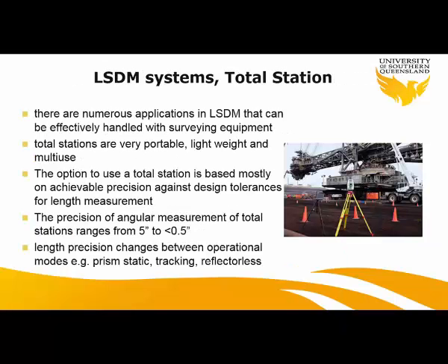The last tool, which we all know, is the total station. You might say a total station doesn't give you that precise a measurement, but we do have what we call an industrial total station, which I'm going to explain. It gives you more precise accuracy for both distance and angle measurement, which enables us to achieve micrometer accuracy.